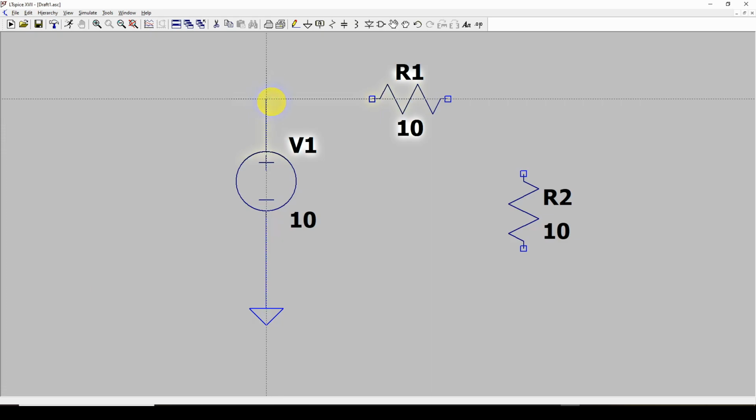and it's smart enough to know that I didn't want to go past the voltage source. I wanted to connect the wire at both sides, at the input and output. So it draws the wire, and then I just go over here. I can go right through the resistor, click, right through this resistor, left click, and then back here to connect it back to ground to give us a continuous circuit, left click, and now we've got our complete circuit. So I right click to release that wire tool, and now we're all set to go.